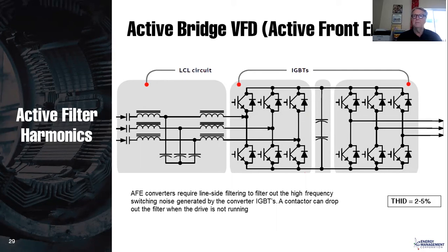That's really nice. However, because these are turning on and off and they're eliminating the lower harmonics, they're great, but every time they turn on and off, they create switching noise. And that switching noise we have to worry about on our distribution system. So we solved one problem, we created another.